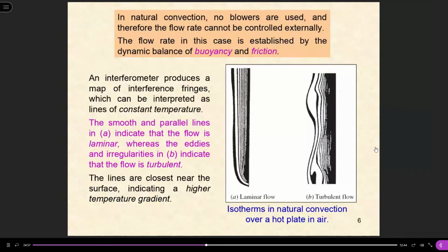So that gives an idea why there is natural convection: it comes from the density difference. Now we also learned how we can calculate the density difference when the fluid is heated. Next, we need to understand what the airflow looks like near a heated plate. In this picture, what you have on this side is a solid, and this side is air.